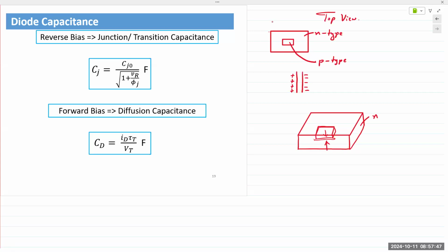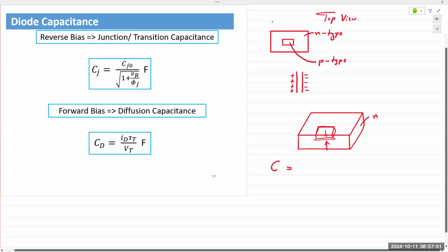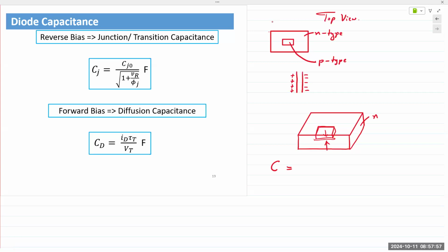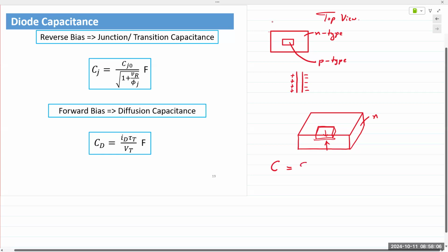Okay, so the capacitance between the two plates would be given by the cross-sectional area, the physical dimensions of the implant, right? And that would basically be the areas where the P and N-type material are overlapping, right? Two overlapping plates is the cross-sectional area of the overlap. So C would be the standard capacitance formula, epsilon A over D, right?